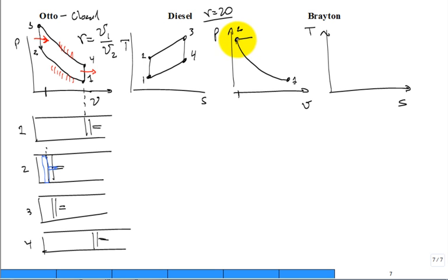So it's constant pressure heat addition, because as it's starting to spray the fuel in, it's burning, it's starting to expand and go into a power stroke. It's pushing down on the face of that piston. So in the modeling, it's not perfectly constant pressure, but we approximate it to be constant pressure heat addition.